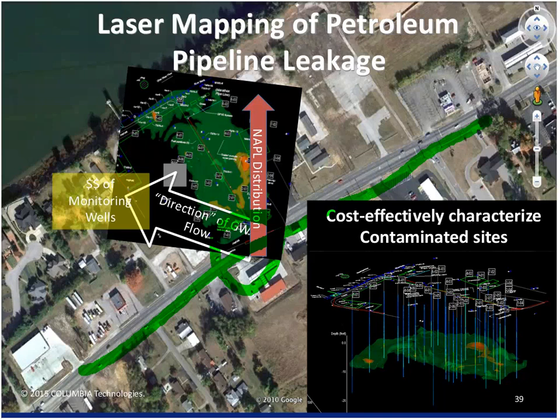So where did the LNAPL go? Well, we went out with the lasers, which is only going to respond to LNAPL, and we found the LNAPL went the direction of the red arrow. So I ask you, why is that? And again, it's this fundamental concept of LNAPL doesn't move with the groundwater until it, A, gets to the groundwater, B, reaches equilibrium with the groundwater, and then C, the groundwater flows in a consistent direction and can migrate off in these transport zones.